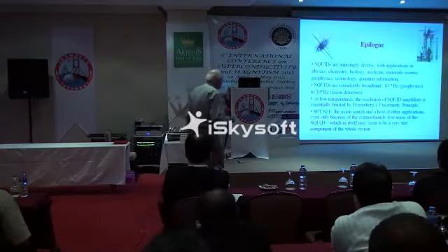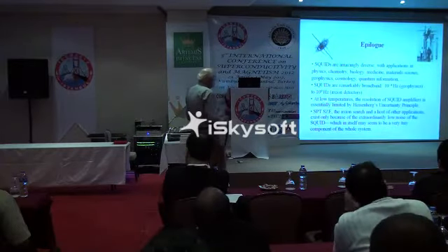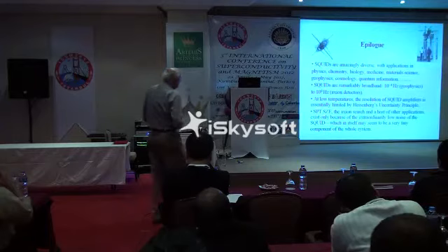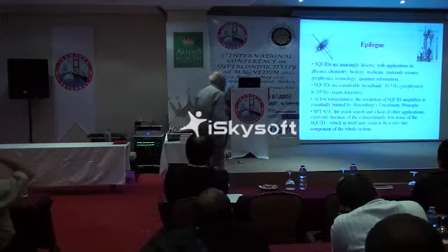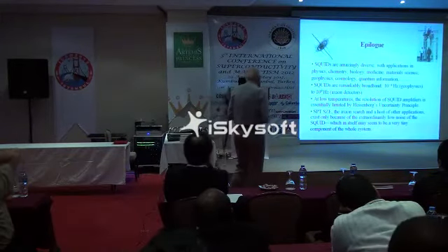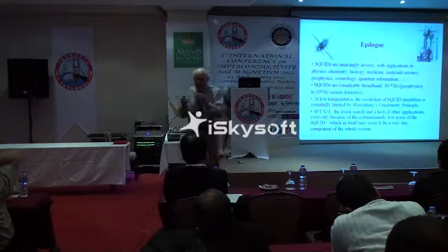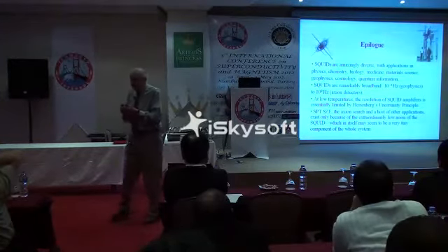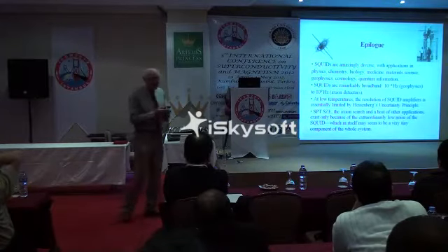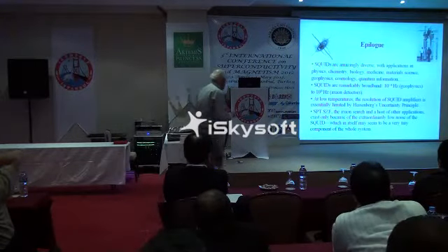They're very broad-band. They're used down to 10 to the minus 4 hertz in geophysics, up to, say, a gigahertz, or even higher now in axion detectors. And at the lowest temperatures, the resolution of the squid amplifier, properly designed, could be essentially limited by the Heisenberg uncertainty principle.